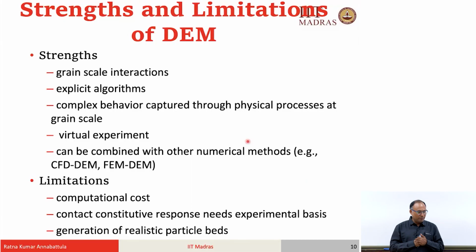For example, suppose you are doing excavation, right, and you want to study how the bucket erosion takes place, how the bucket's wear and tear takes place as a function of interaction between the particles. That is something that you can do by coupling FEM and DEM. There are several other applications that you will come across which use the strong coupling between these kinds of methods. However, although it shows a lot of promise, it also has limitations.